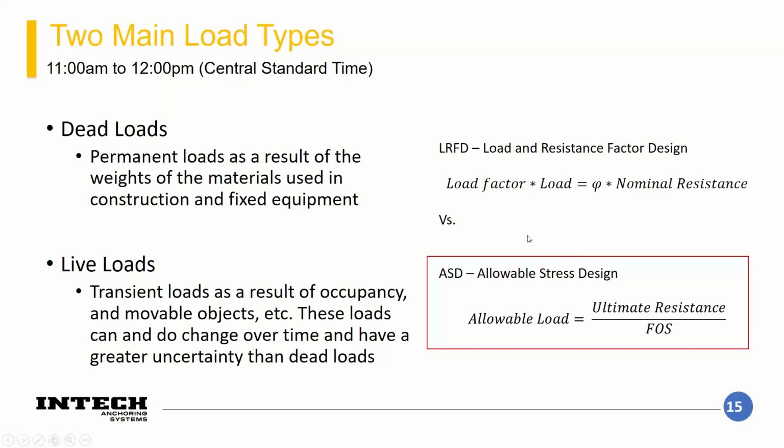and I won't stress on this too much. Foundation design is almost always going to favor using an ASD approach rather than an LRFD approach. From here on, we're going to be discussing this from an ASD mindset, where we're talking about allowable loads, ultimate loads, and a blanket factor of safety.